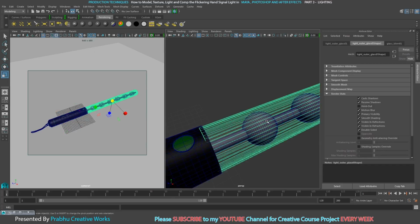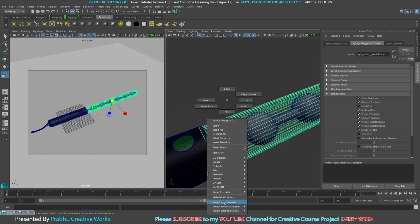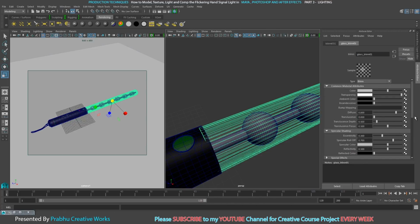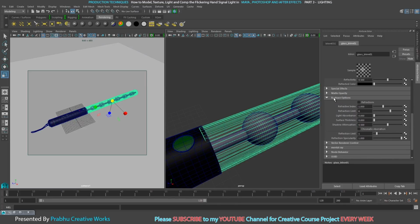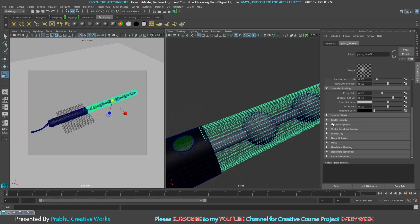So I will select this one, right click and choose material attributes. I will go through the material. Here you have to go downside, here you have the ray trace option. So you will expand this ray trace option and turn on refractions. Now I want to give some more refraction, so I will give 1.3 or so. What it does for us is bend the light and show the glass material as real.